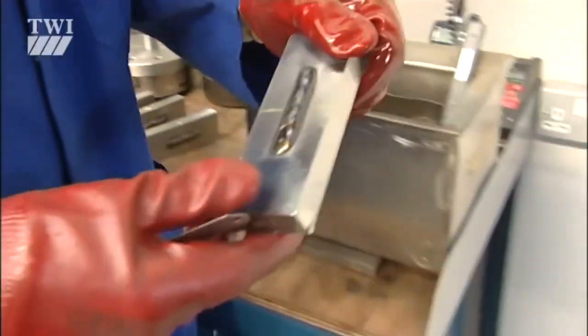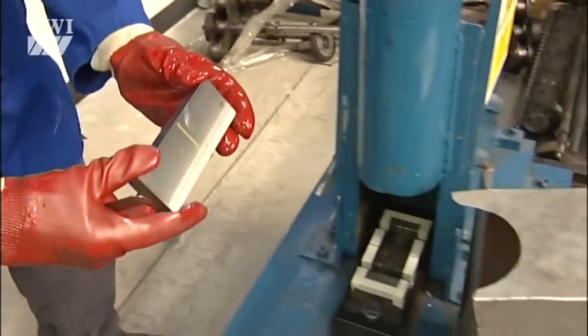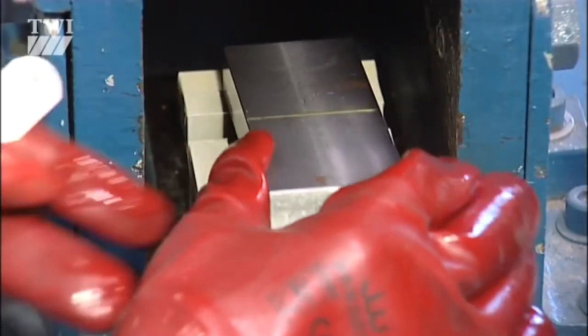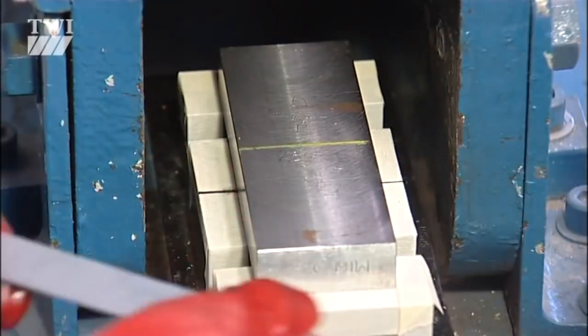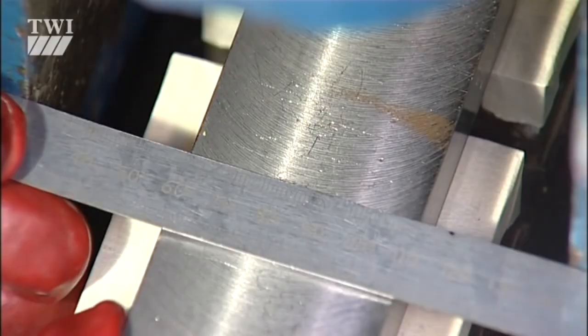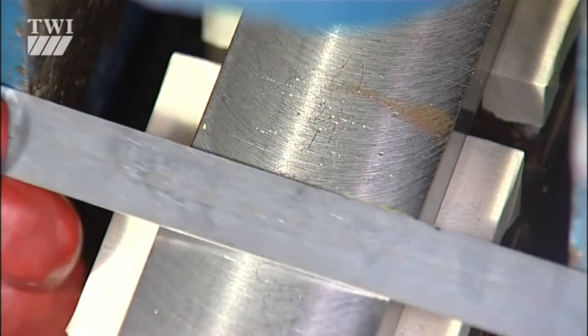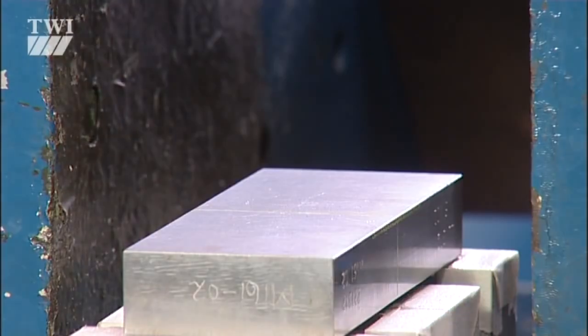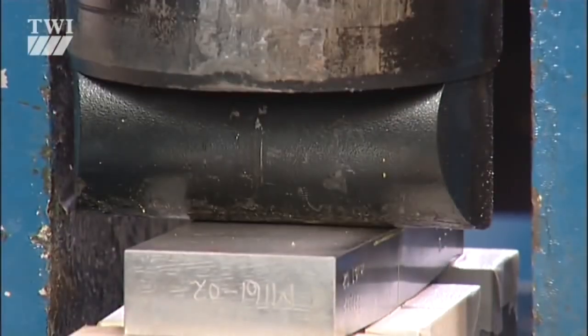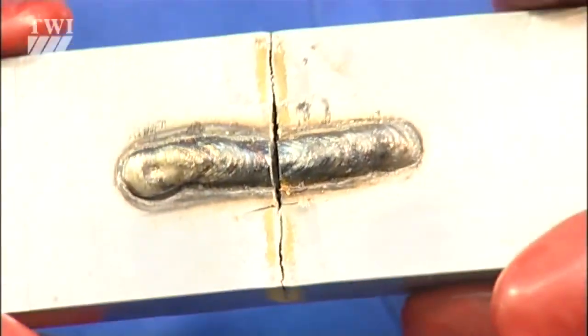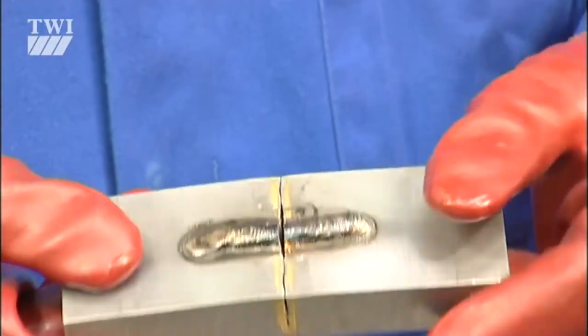A brittle crack is introduced on one side, and the simply supported specimen is struck in a standard way. The test is carried out on a number of specimens at progressively lower temperatures until the test piece breaks in a brittle fashion. This is known as the nil ductility temperature, or NDT.